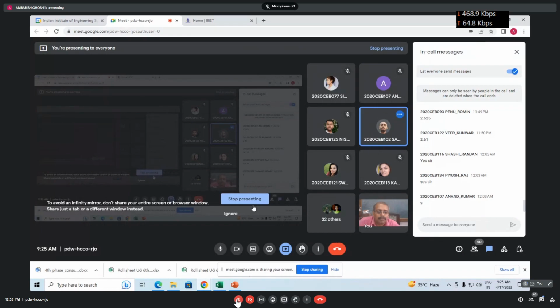Pile diameter, you see, depending on the soil profile, you will calculate from the superstructure, they will tell the load that will be coming. When the column load is given, and moment is given, then you have to assume a pile group. In the pile group, then you have to calculate the load that is coming on the extreme pile. That will be explained in the next semester.